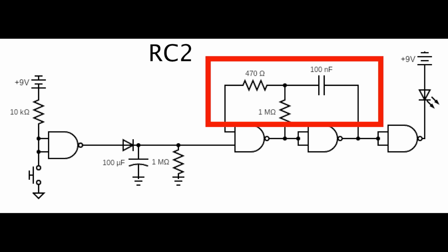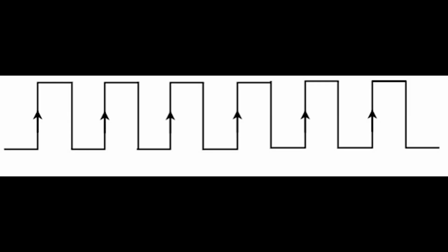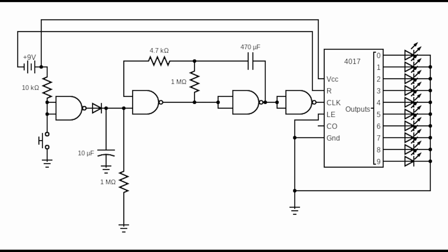In this part, we use a 104 capacitor and 3 more NAND gates to create the oscillation. As long as there is half the supply of voltage outputted by the capacitor, the NAND gate oscillator will produce a clock signal. This circuit is connected to a 4017 decade counter.